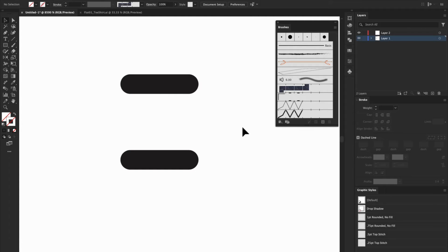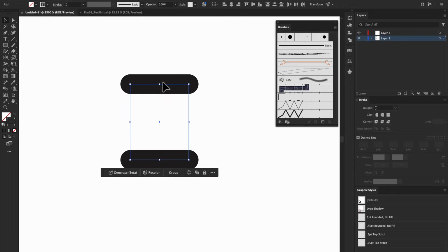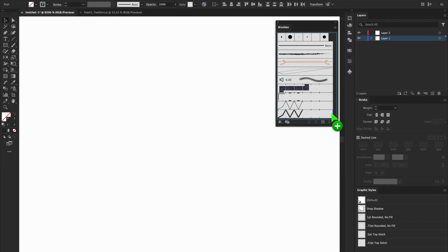All right, now we're finished with the art that we wanted to create. We've made a bounding box around exactly the pathways. So the program understands exactly what we're using. And now I'm going to select all of this. So I'm just going to drag a marquee box around both of these stitches, right? So now everything is selected, and I'm going to drag it into our brushes panel until I see this blue line appear at the end of this stitch. It doesn't mean that it's going to add it to this stitch, it's just going to add a new stitch to our panel.